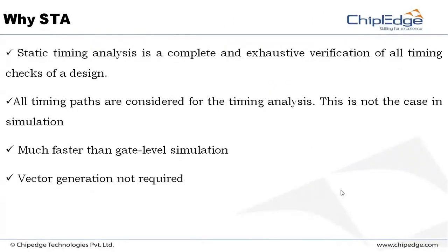Why STA? As I told, it is a complete and exhaustive verification. It's not like you give test vectors and it will test only limited portions, not all the paths in the design. So all the timing paths are considered during the timing analysis. But this is not the case in simulation. When you give simulation, you give input vectors, right? And it will test only that path. You are given some input, so whatever gates come into play for that input, only they will be tested.